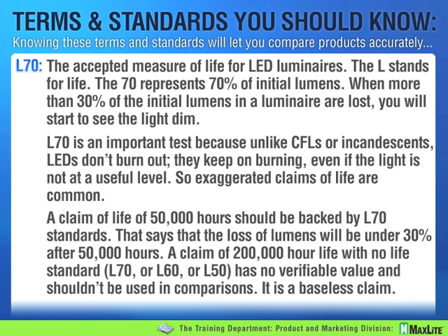What's determined is it's generally accepted that 30% depreciation of original light level is where the fixture is no longer useful. I happen to know that there are large, very green Fortune 100 companies out there where they have their own standards like L60. They feel that when the fixtures have depreciated by 40%, it's time to replace them. So what you need to understand with LED is it's not just a number of hours that this product lasts, but what happens at that number of hours.